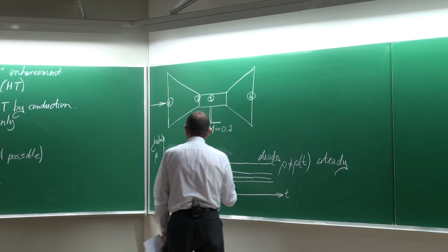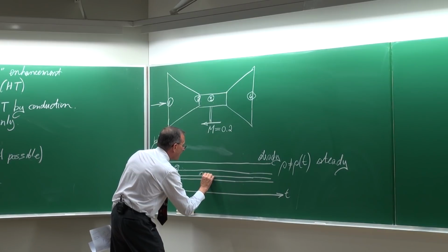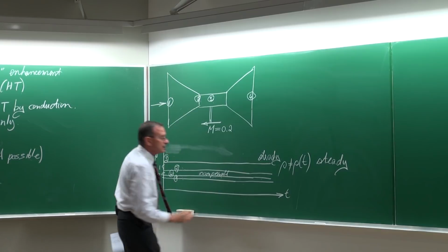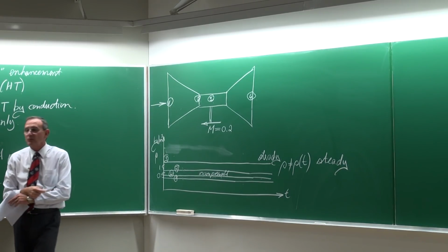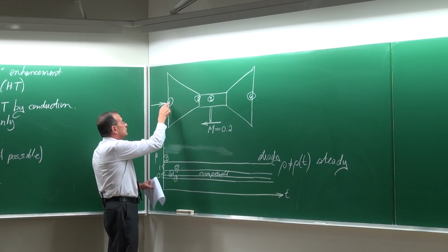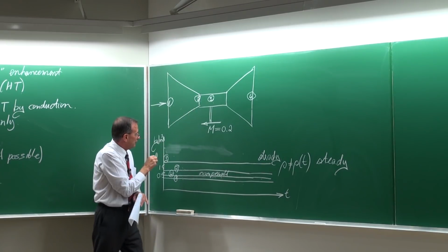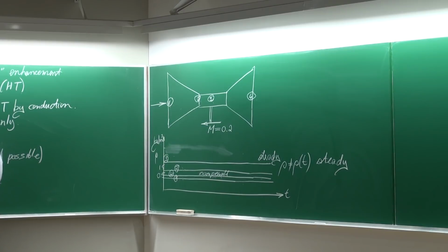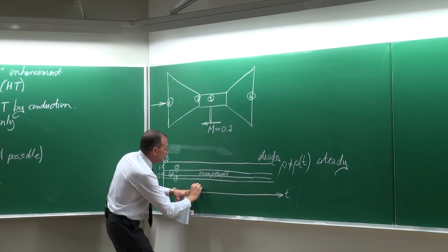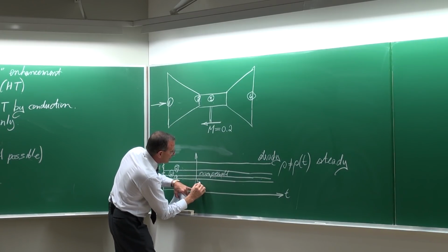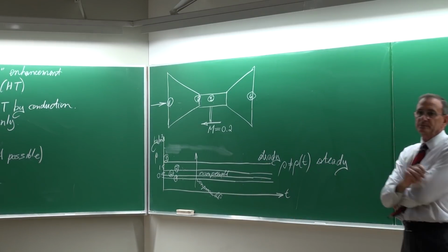Also, what we now can see is that at measuring station 1, we can consider the fluid to be incompressible. It hasn't been compressed. It's this atmospheric air. And if you keep on measuring the density there, it is not going to change. The same at measuring station 2. If you stand there and you measure the densities all the time, it's going to be the same. Except now if you're a molecule and you move right through the turbine, you're going to go through a process where the flow would be compressible. It's going to be compressed. And then here on the outside again, it would be incompressible. Okay?